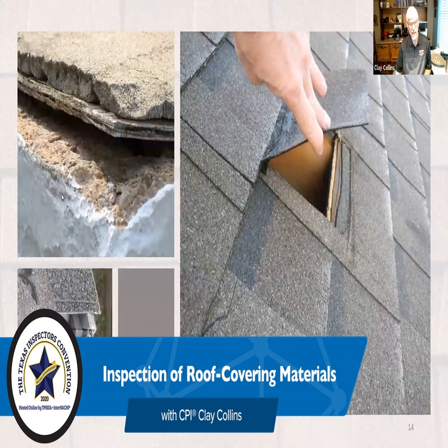So you can see down here, that one covers this, so there's your 2 rows, but up here, it was too high and it missed it. So this one only has 1 row of nails. You're going to see those when there are problems. Well, here, they didn't put it where it's supposed to be, so it was between the tabs.